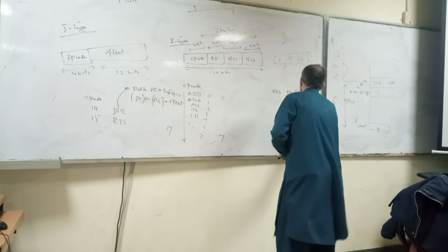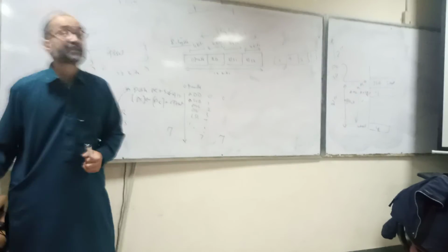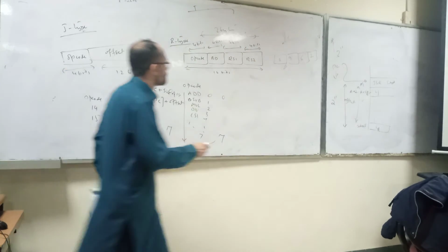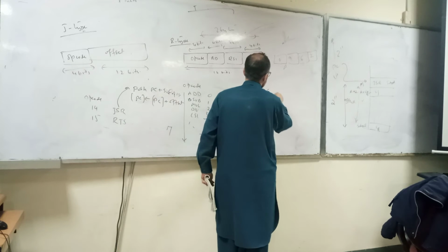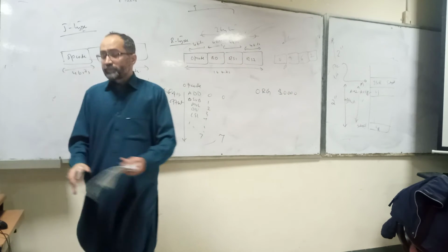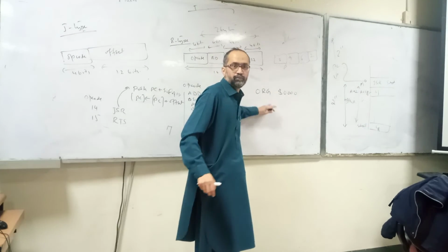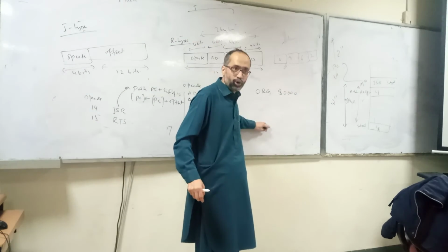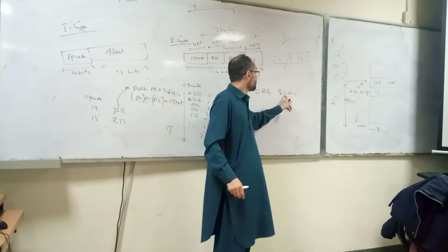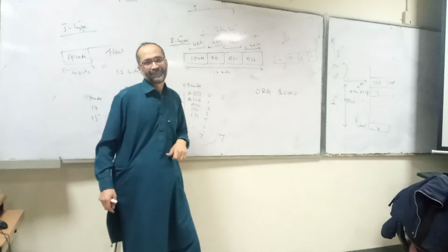Okay, now if you look at any assembler, it also knows the starting address from where you will be compiling your program. So let's assume this instruction is called ORG 0000. This means that whatever code you write downward will start at address 0. So it is the address of the first instruction.